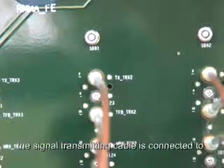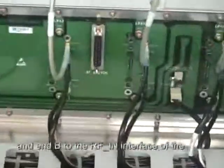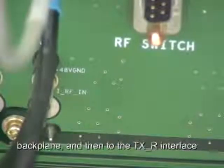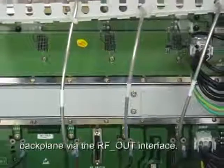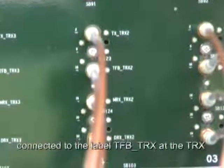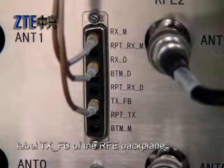And A of the signal transmitting cable is connected to the label TX-TRX of the TRX backplane, and end B to the RF-in interface of the corresponding HPA board of the HPA backplane, and then to the TXR interface of the corresponding RFE board of the RFE backplane via the RF-out interface. And A of the 10 MHz clock cable is connected to the label TFB-TRX at the TRX backplane, and B to the corresponding label TXFB of the RFE backplane.